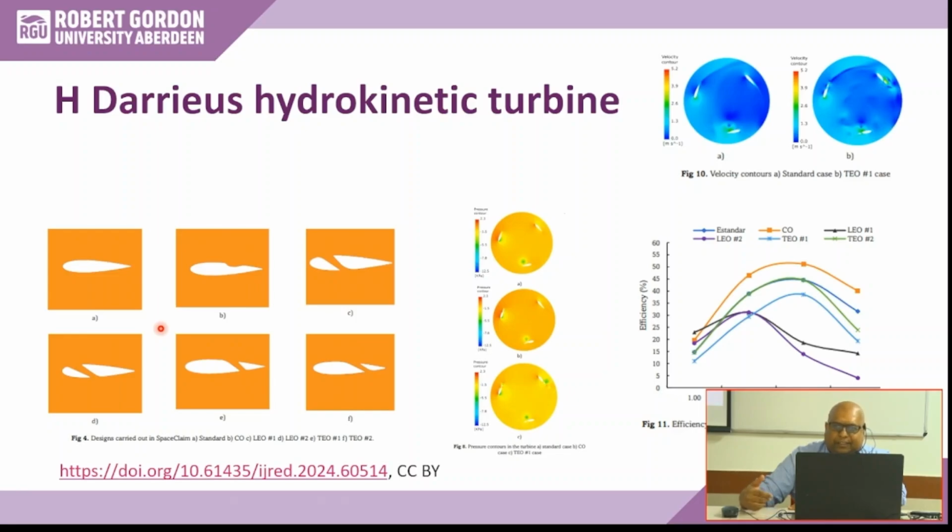Vortex generator is the other word we used. On top of the blade, you can have a vortex generator to influence the flow separation. You talked about flow separation, right? Yeah, so a vortex generator will also help mitigate flow separation.